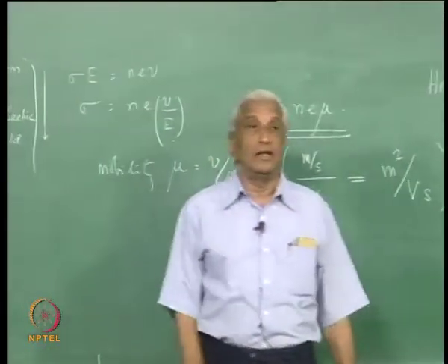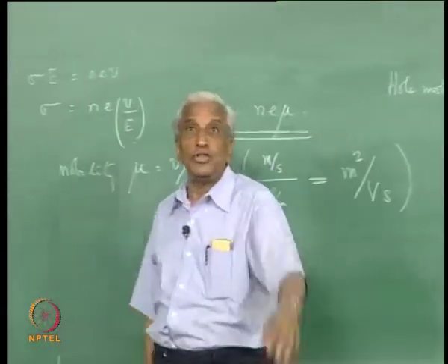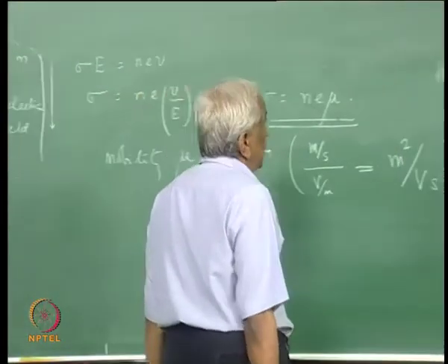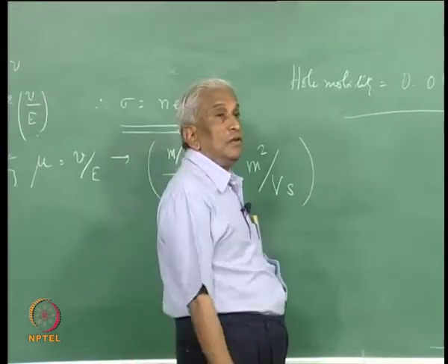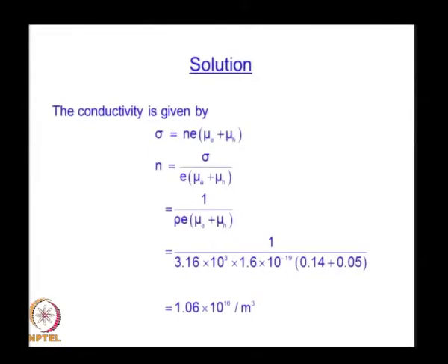Both contribute to the current density, and since the hole is positively charged and moves in a direction opposite to that of the electron in the given electric field, the current densities due to both electrons and holes add up. Therefore, we have a general relation: J is N_e e mu_e E plus N_h e mu_h E, where E is mod E, the sign of the charge being included in the directions.